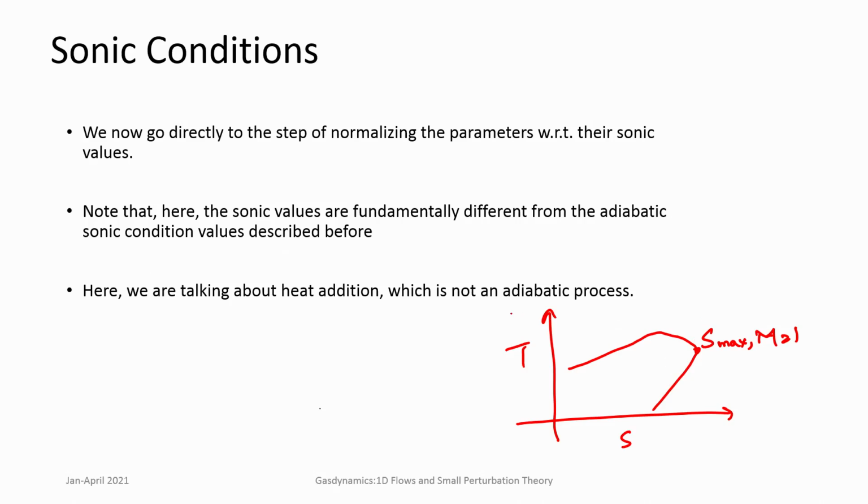So, for Rayleigh flow it is possible to take the reference as the condition where the flow goes to sonic. But what we should really underline is that the sonic values referred to in Rayleigh flow are fundamentally different from adiabatic sonic conditions.